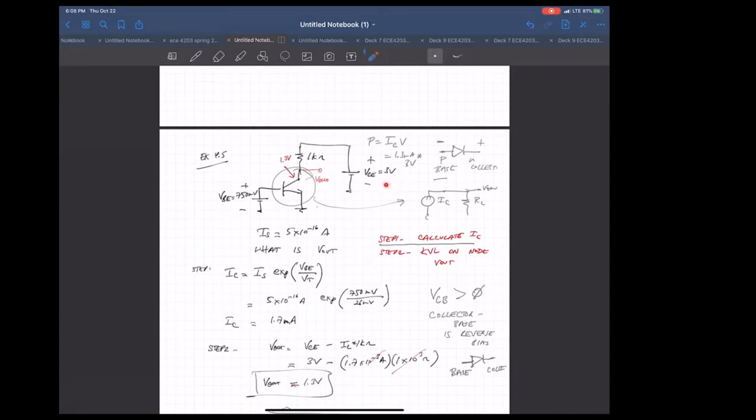The first 100 units might be 3 volts. The 101st through 120th unit might be 2.9 volts. There'll be variations. Same with these resistors: depending on the type of resistor you use, and the I sub S in your transistors, there'll be some variation when you build your product. So you want to build in margin so that you keep this in forward active.